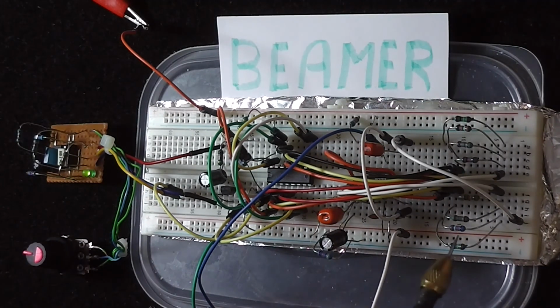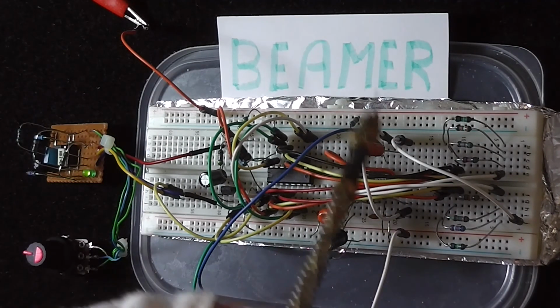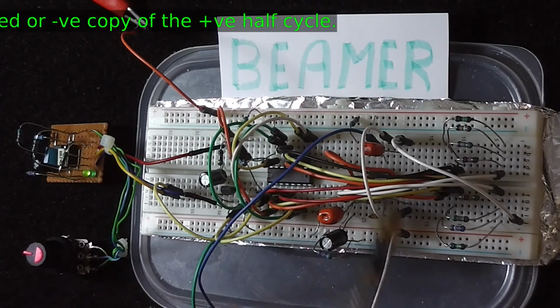Okay, moving on to the right hand side of the breadboard is really the business end, and you have 8 resistors here which define the positive half of the wave. The negative half of the wave is a duplication, a copy of the positive half.